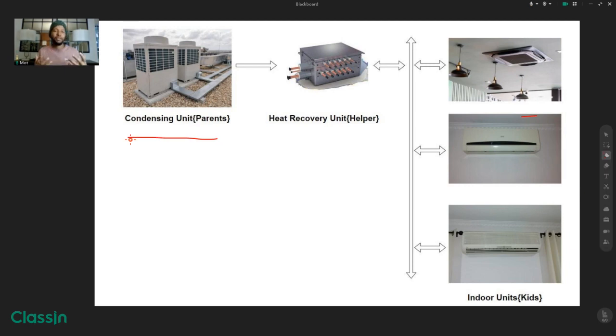And there are quite a number of considerations in how you're supposed to locate or put where your system is going to be located, depending on how high your building is, depending on the run. Run means the length of your piping from the condensing unit to the indoor unit, how the air would circulate, and if your outdoor unit exceeds the space that the manufacturer wants your unit to be installed, how are you going to help it not to short circuit that air?